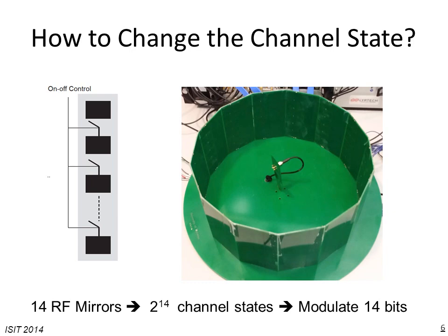By introducing 1 bit of information in the I by inverting its sign, and another independent information bit in the Q by changing its sign, we can make the constellation carry 2 more bits of information and also make it symmetrical with respect to the 4 quadrants.